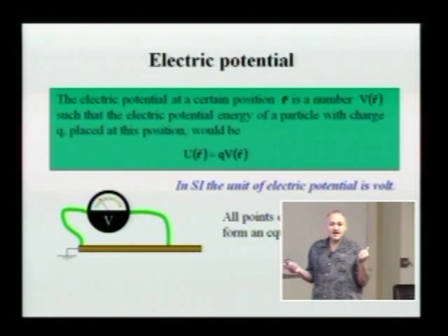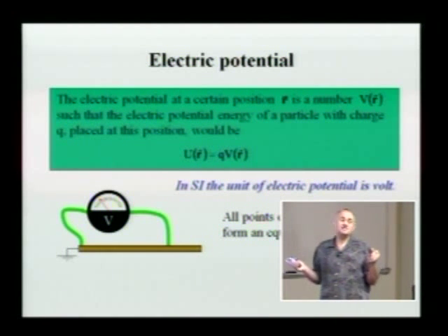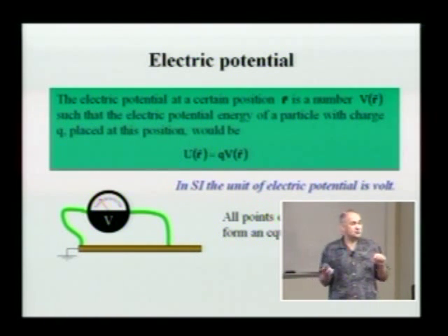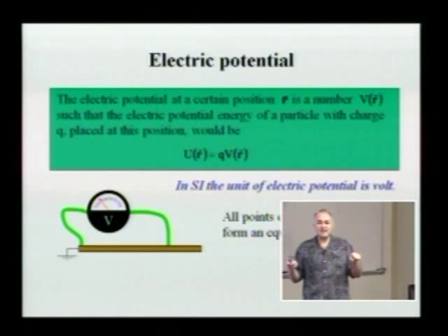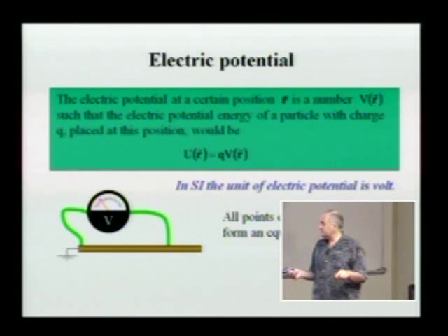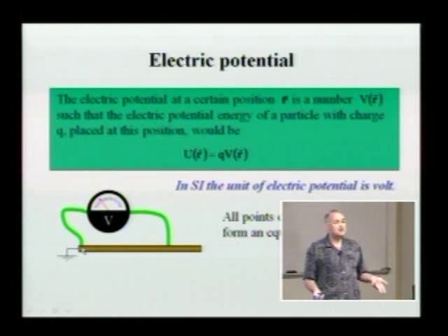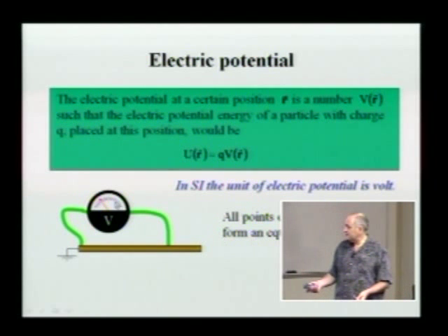The voltmeter, as a device, is actually used to measure something other than potential as well. It is used to measure potential differences between various points. It always measures the potential difference between the points which you touch. So if one end touches a point where potential is 0, then the potential difference between these 2 points is equal just to the potential at that point.